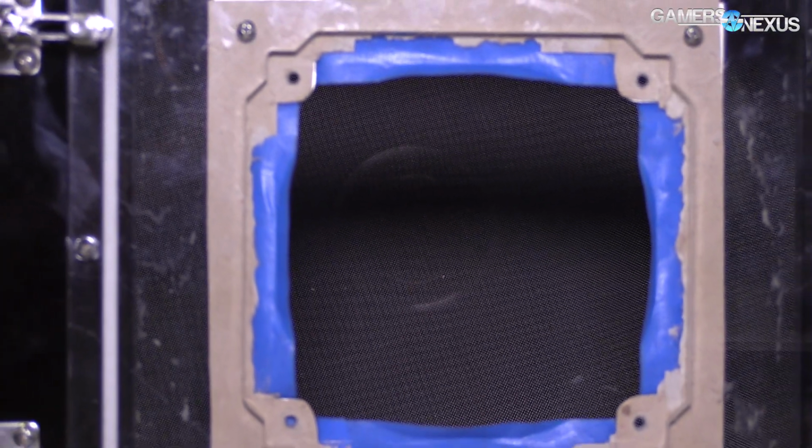Inside here there are several screens. Those are to diffuse the flow so that the air flows at the same speed through the entire diameter of the wind tunnel. That's necessary for the calculations because the math makes certain assumptions about the diameter of the wind tunnel and how fast the air is flowing. These 2 pressure taps here are differential. They're measured against each other. This is the high side pressure. This is the low side pressure.